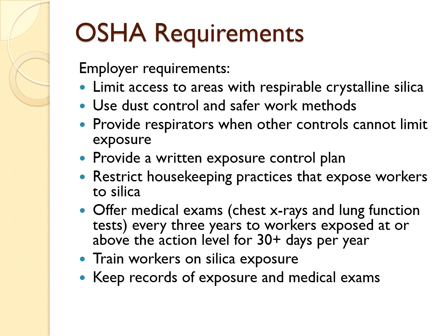OSHA requirements continued. Employer requirements: limit access to areas where respirable crystalline silica is present. Use dust control or safer work methods. Provide respirators when other controls cannot limit exposure. Provide a written exposure control plan. Restrict housekeeping practices that expose workers to silica. Offer medical exams, chest x-rays, and lung function tests every 3 years to workers exposed at or above the action level for 30 plus days per year. Train workers on silica exposure. Keep records of exposure and medical exams.